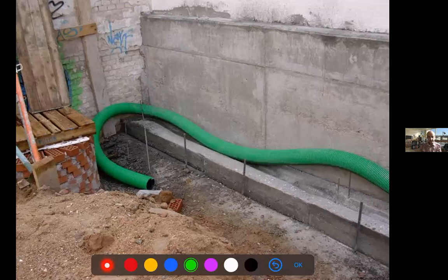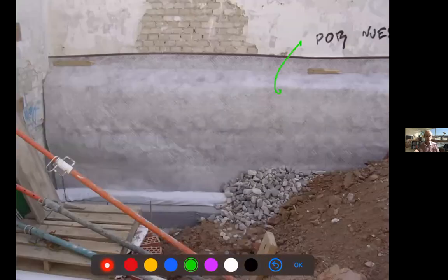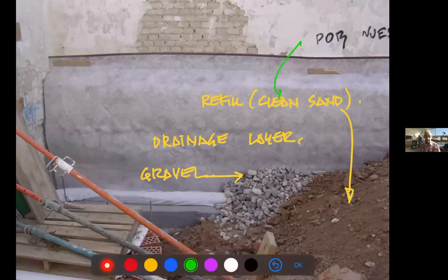You see here that kind of porous pipe with a drainage, which will be connected later to this kind of drainage wall later. You see, this is a different kind of a drainage layer. And see the gravel, just to make sure the water does not clog in and goes to the pipe. And you don't clog it with the sand, right? And this is important, I put clean sand, because sand for fields, you have to buy clean one, not contaminated.